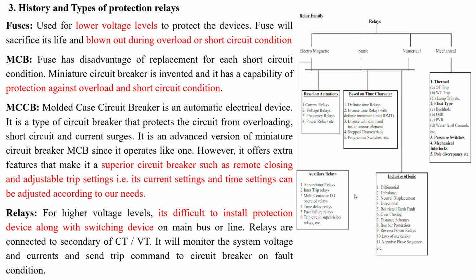But at lesser voltages, fuses, MCBs and MCCBs are protection devices as well as switching devices. At higher voltages, circuit breakers are only switching devices, and the combination of relays as well as CTs and VTs are just measuring devices and sensing devices of faults.